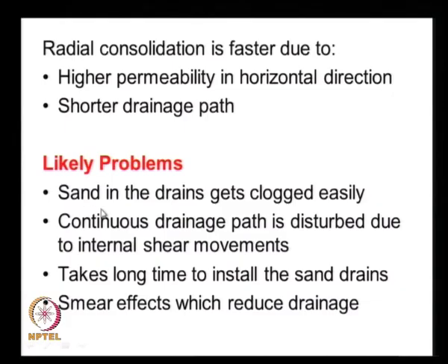The sand within the drains gets clogged easily, because the soft clay may have very fine particles, and in due course the fine soil particles come into the sand and clog the openings,